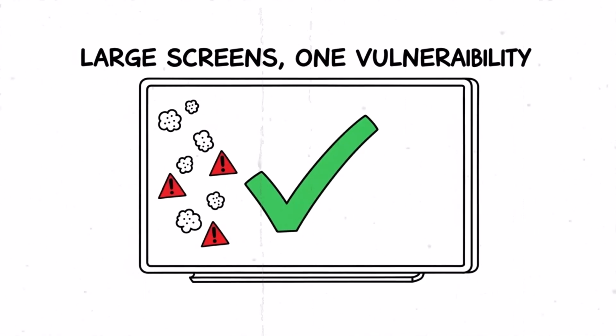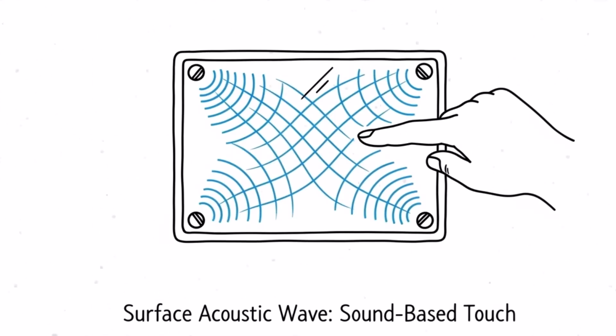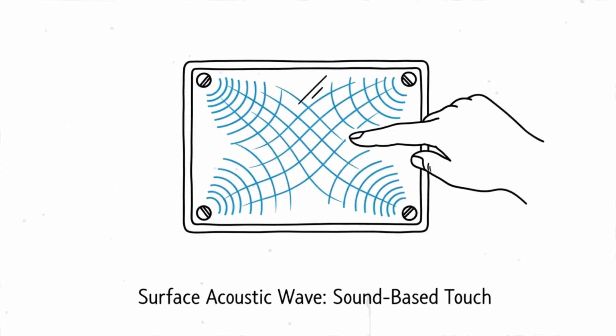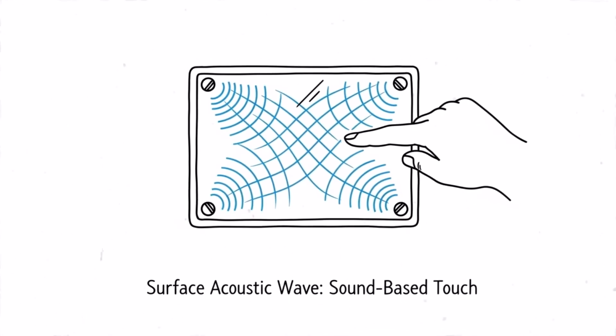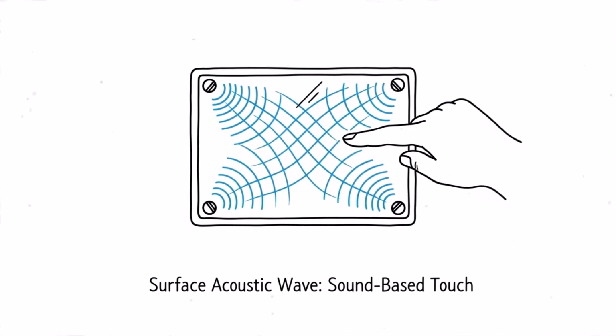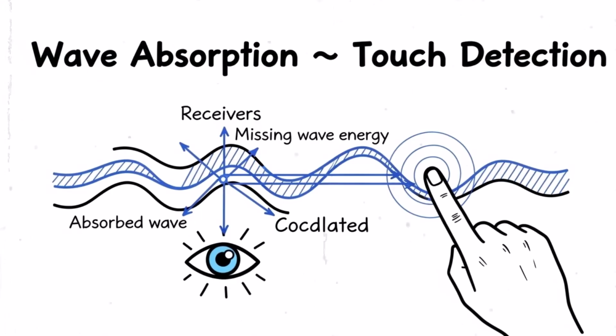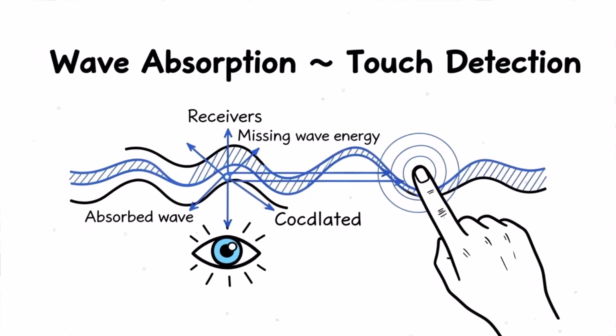Optical touchscreens use cameras placed at the edges of the screen. These cameras detect shadows or reflections caused by touch. Advanced algorithms determine the exact touch point. Optical systems are common in large interactive displays and collaborative screens. They allow multi-touch and stylus input without special coatings.